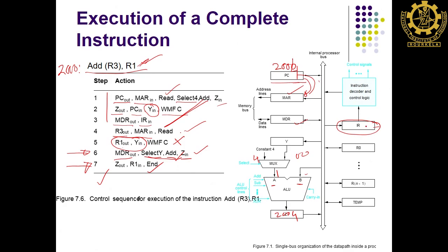After decoding, this is the instruction decoder. From here the output will tell that this is the offset where to jump, and then it will be added with the program counter present value. So, program counter present value is here. Instead of bringing it from the program counter, what we did was we loaded Yi here. So the Yi is already here, and then this offset will come here, then Yi will come here, and then you simply add these two: the offset and the incremented program counter value.